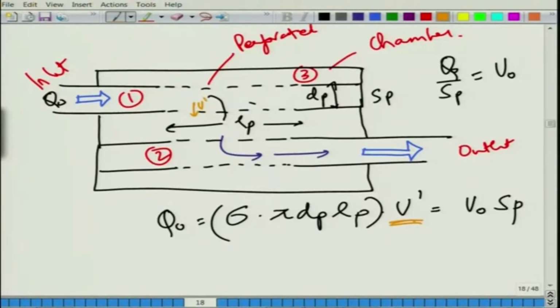Again this u dash will tend to be more as the flow goes along this direction for this configuration, and as we approach this hole, it will tend to be 0, and finally the grazing flow tends to be significantly different from non-zero, that is this value approaches this value more towards this direction. Again there will be some losses, so whatever u naught we are seeing here will not really be the case here. You will get a slightly lesser velocity here because of losses. That is what happens in the real world.